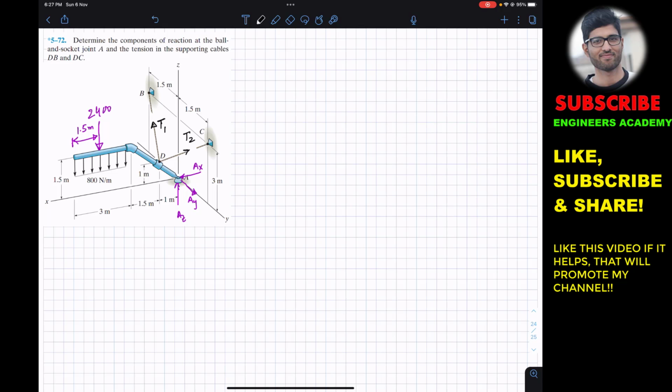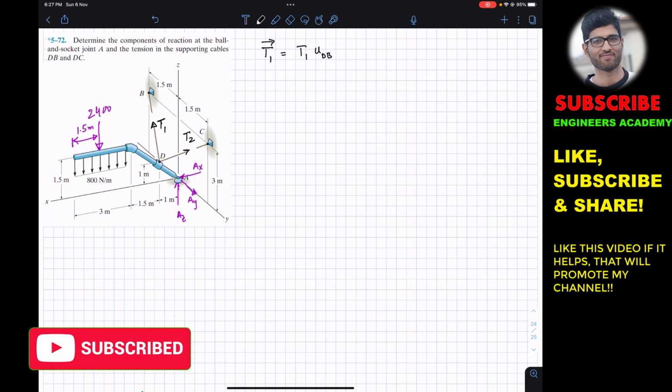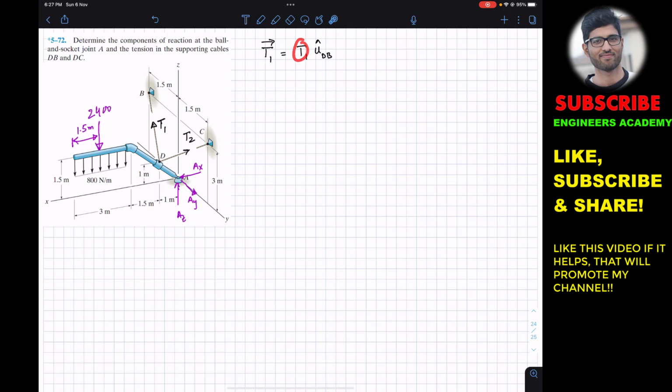Now, in order to solve this problem, first of all we have to find T1 and T2 as Cartesian vectors. So first I will write the T1 Cartesian vector. This will be equal to T1 magnitude times the unit vector from D to B, since T1 is acting from D to B. The unit vector is the position vector from D to B divided by the magnitude of that position vector.